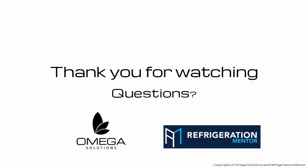So those are just two key points that I realized recently. In the old days we had critical charge systems, but just recently I've been at the forefront of the literature on inverting suction piping from liquid migration on transcritical CO2 at the compressor. The one you're referring to is on a suction header, of course. Yep, we've seen that before, but specifically that inversion. And then the second is insulating the liquid line or drop leg from the condensers, right?